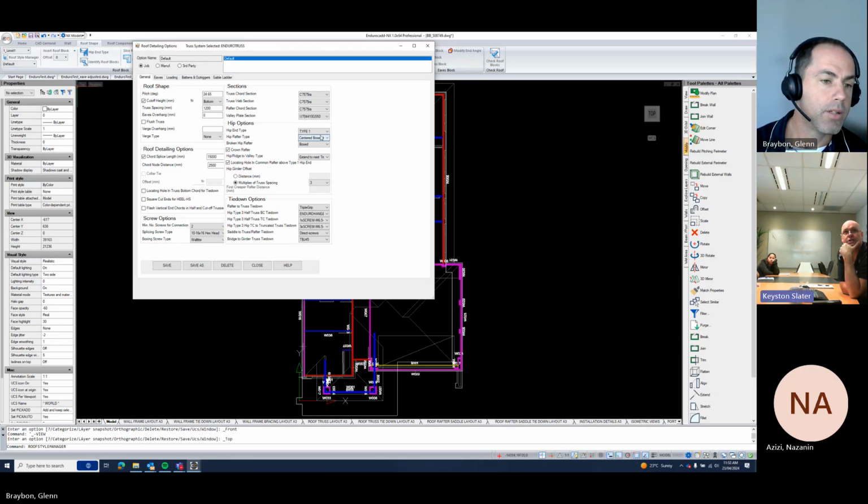If we've got truss direction change and one roof plane is split to be half hip, half rafters, half truss. Yep. Then we're sort of backwards and forwards in the loading parameters. Changing the hip end types or the roof face type. Yep. Hip end types will be different. That's adjusted in the hip end type menu here.